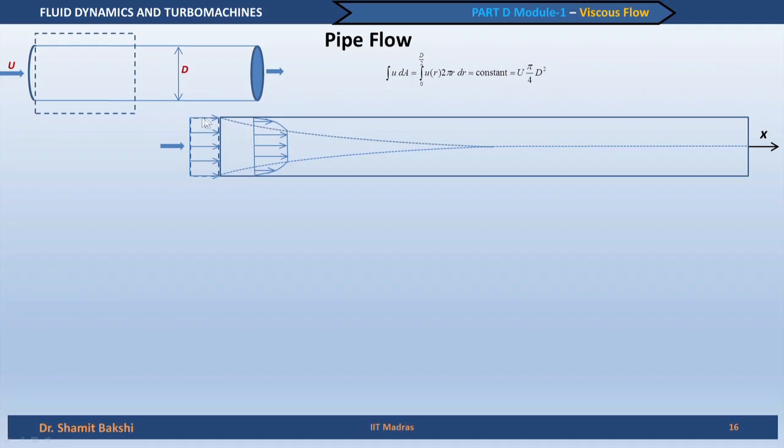So basically the flow near the solid surface decelerates, the velocity is 0 at the solid surface. Naturally the presence of the wall retards the flow. But what happens more interestingly is that the central part of the flow now has to compensate for the lowering of velocity near the wall.